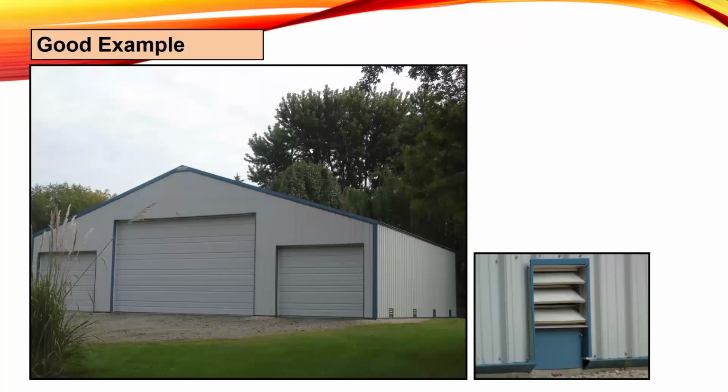So this is a good example. There are no size requirements for agricultural structures. They can be any size as long as they're meeting the ratio by having enough flood openings. So this one is built at grade. It's wet flood proofed. It's made of the right materials, presumably anchored and low damage potential.